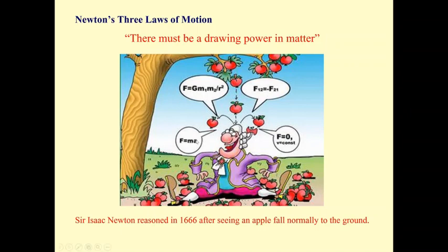And when the a is 0, that means when the structure is static or the structure moves with constant velocity, we get the second Newton law: summation of force equals 0. We use the second law a lot to determine the reactions, and to determine the internal forces and internal moments of the structure. And we use the forces and moments to design the structure, to design the machine.